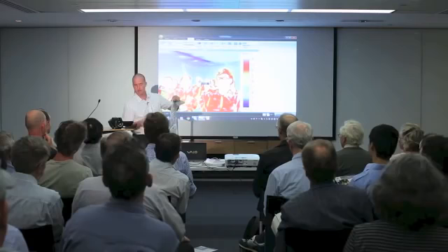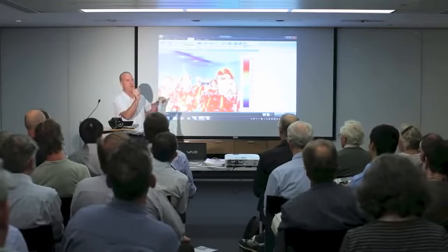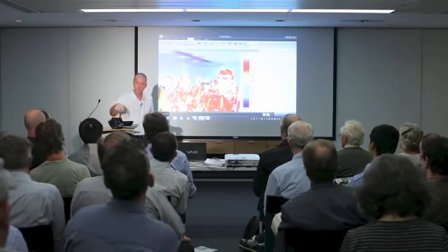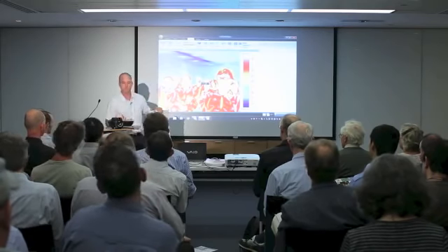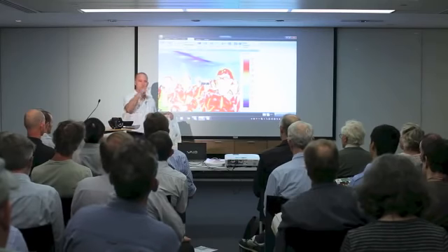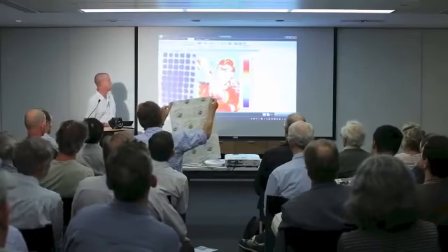A thermal imaging camera basically has a whole array of little tiny sensors called microbolometers, and they detect temperature. There's a crystal lens there that focuses the heat on it, and then it turns that into a picture. So I've calibrated it to see cold to hot between about 20 and 35 degrees, which is why people are looking white, because they're above 35. If you take that sheet there, sir, and hold that up in front of the camera for me. You see the temperature of the mat is much cooler than the room.